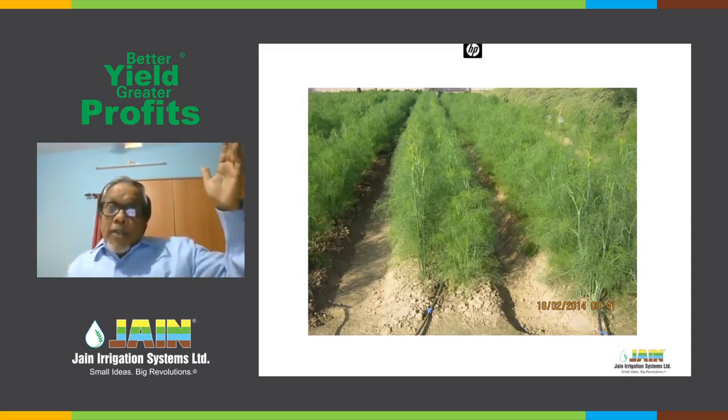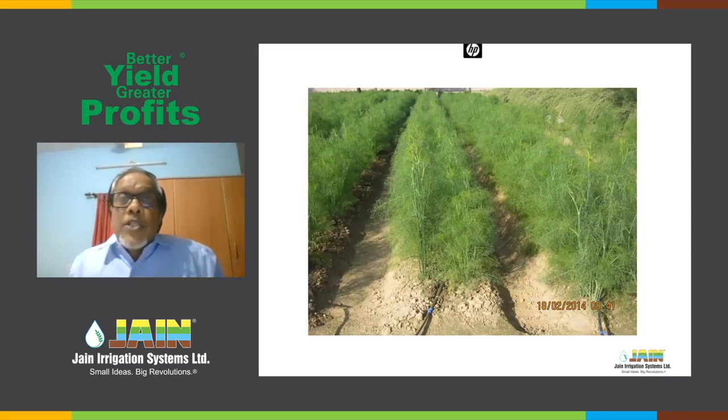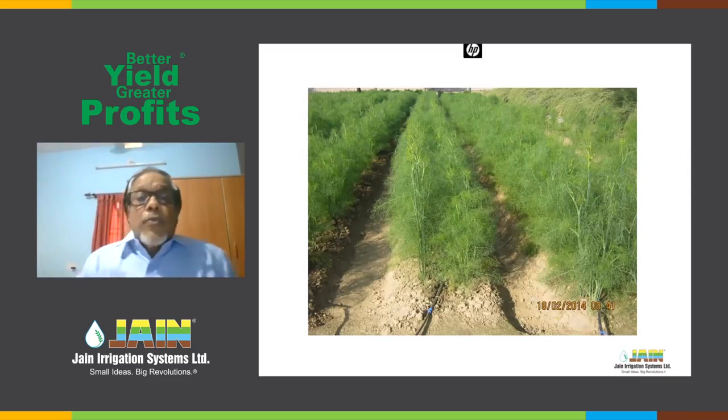So why in this case, if you compare with the first picture I showed you, with the strawberries with so many drip lines, a commercial trader would like to give 2 or 3 drip lines for this, or at least 2, because 2 rows of plants they will give 2 drip lines. I don't, because the growth is good, uniform, even with 1 drip line for the soil. This is exactly the optimization, cost and material optimization, avoiding extra plastic to the ground and becoming affordable.